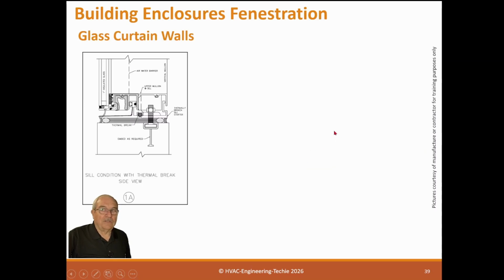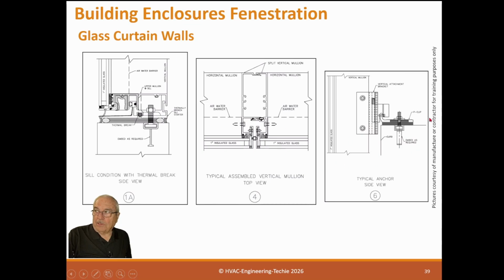Curtain wall basics. These curtain walls are actually hung off the structure. And here's the three things we're going to talk about. Here's how it's hung. This is the aluminum frame of that window wall. It has a mounting bracket, and it mounts back to a structural element. You can see it's not actually sealed. Here's the glass out here, and you've got an opening here that will allow sound and air between them, so if they don't want that, there has to be a seal placed here. So that's important to understand.